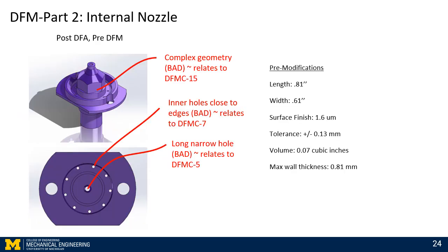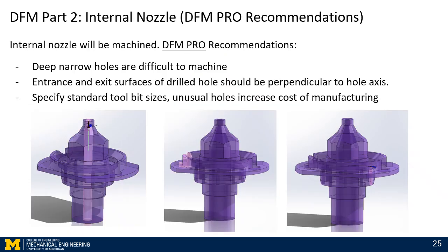Our initial design before design for manufacturing had some complex geometry that added time to the tooling, inner holes close to the edges, which is generally bad practice for DFM, and a long narrow hole, which is also bad practice. These bad design practices were corroborated by our analysis in DFM Pro.